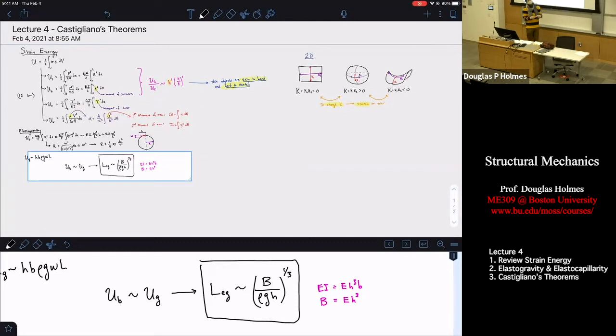So you might want to make a new fancy atomic force microscope with a new cantilever, and you want it to be incredibly light and have these special properties, made of some special material. You might ask yourself, is my cantilever going to be perfectly rigid? Or is the new material I'm using going to cause it to bend a little bit under its own weight? You don't want the latter, because if you don't have that in your model, then you're going to calculate the wrong deflection as it shakes, and you're going to calculate the wrong surface topography of the thing you're trying to measure. So this can tell you whether your object is deforming under its own weight or not.